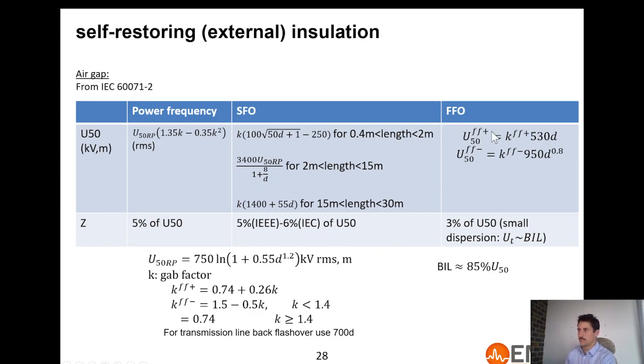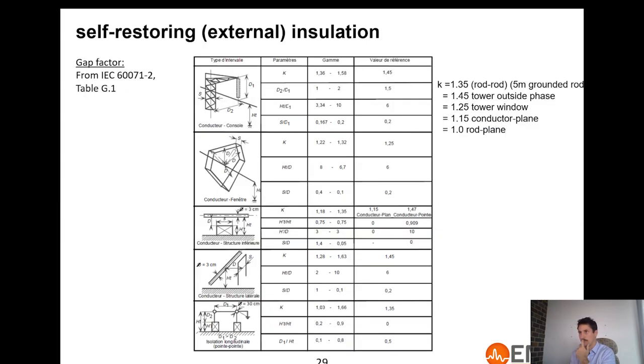Second thing to notice is that it seems you have some signs, and it seems you have different withstand voltage if the surge is positive or negative. So that's something also to consider, and it's something which is true for lightning: the sign matters. If it's negative or positive, it's not the same. So keep that in mind and we'll come back to it later.